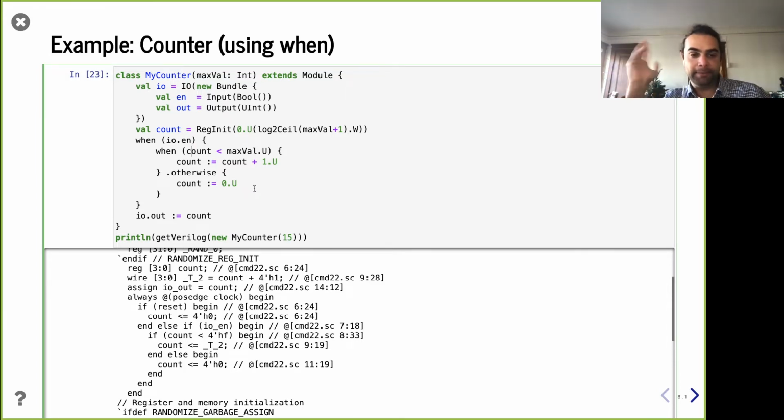But really what I want you to think about when you think about Chisel is, rather than worrying about all these constructs, think more about, okay, I'm trying to build this hardware design. So imagine I have this block, I have this other block, connect them together, right? So all you're doing is instantiating things and connecting things. And there are just some nice features in the language to make it easier for us to express these things, where rather than having to say, I want thing A, thing B, here's a mux to choose between them, I can say, you know what? I'm going to use a when block to do that in a more readable, more graceful way.